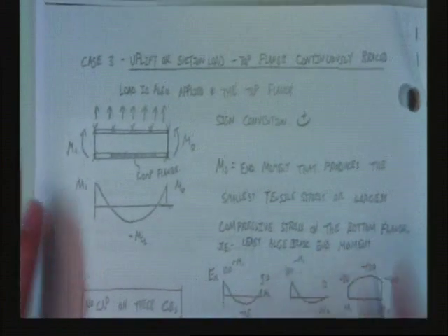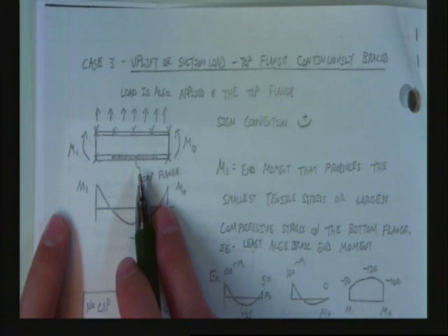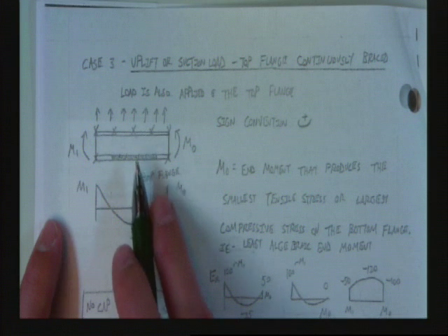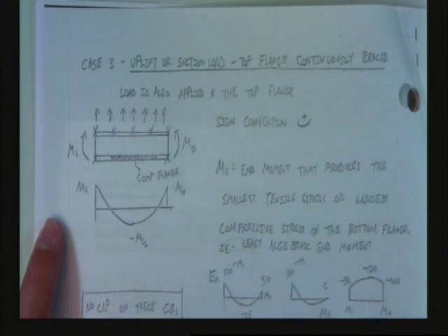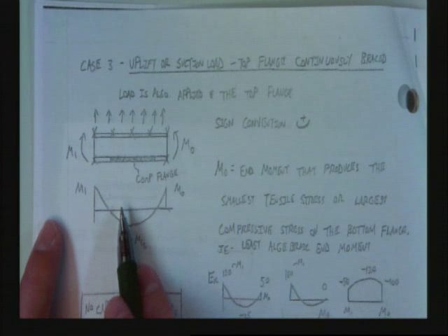Uplift, or suction load. When does this ever happen? Seismic, no. Not usually. I mean, maybe. You do have a vertical component for seismic, but it's not a lot. But you're on the right track. What other events are there out there? Wind, suction. Happens all the time in structures.